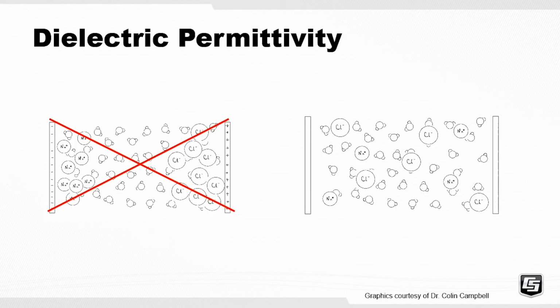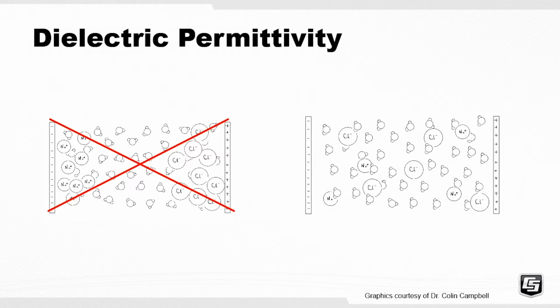In contrast, sensors that measure the dielectric permittivity don't usually have the same polarization issues seen in resistance sensors. They still take advantage of the dipolar nature of water. They emit pulses, and the water molecules briefly realign, as shown in this graphic, and this causes a measurable change.